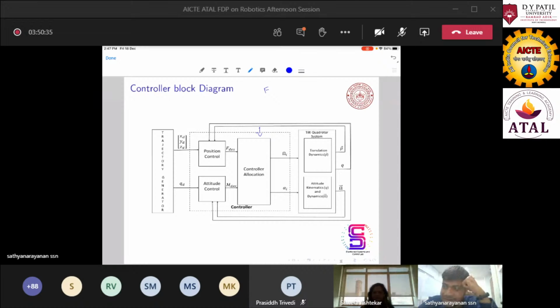So I think you can use adaptive control, as my suggestion will be on that, and you can refer to some adaptive control on quad rotors. There are a lot of literatures where they're tuning. They have used some kind of gain scheduling techniques to estimate the gain for PID. So you can use them also. But as far as I know, I don't know how online you can change the KP, KD values. It's very difficult for me also. I've not yet explored that. So yes. Okay, thank you, sir.